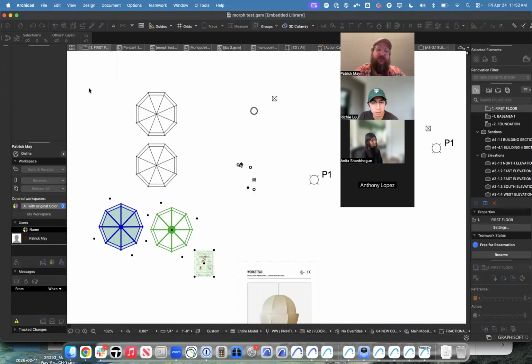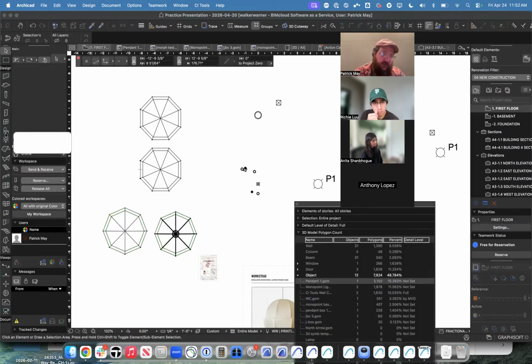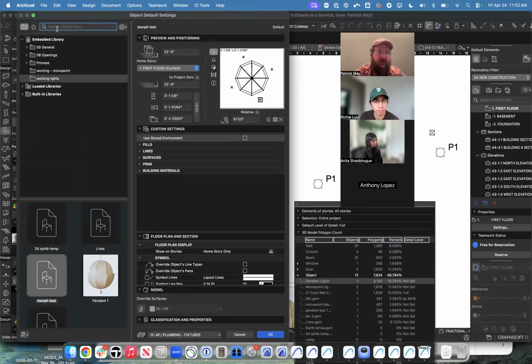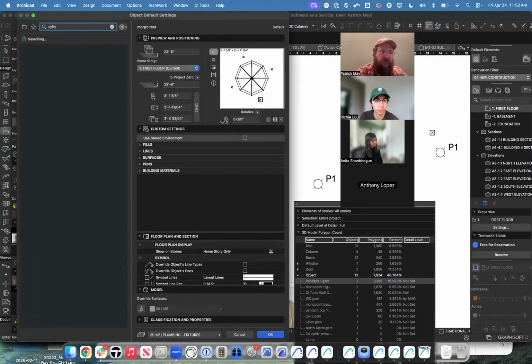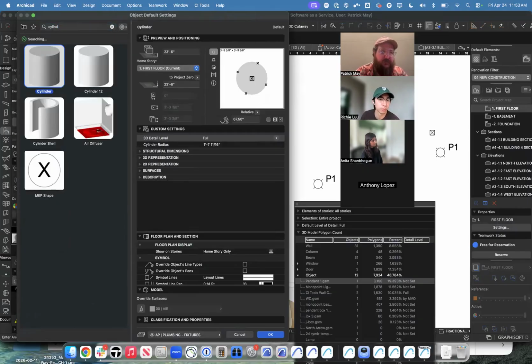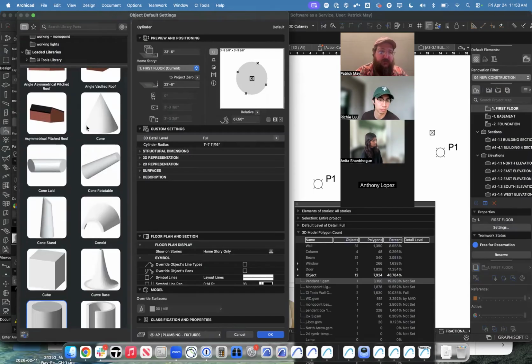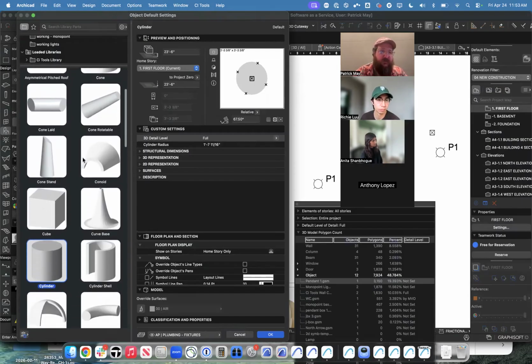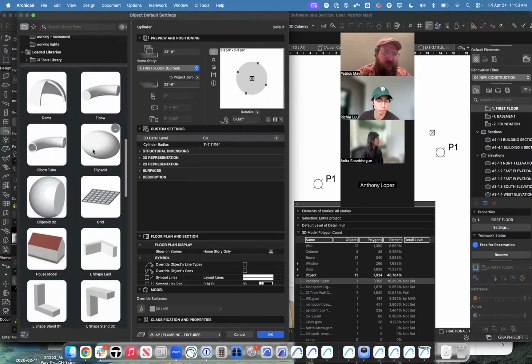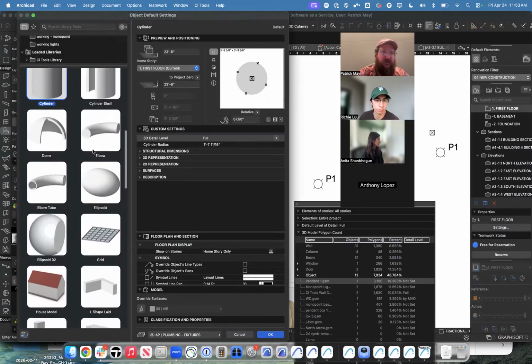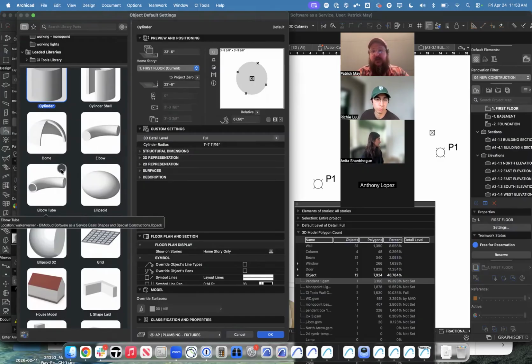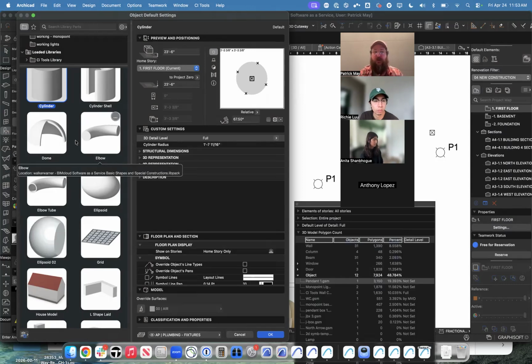Another thing that's useful for creating these objects is, in the object tool itself, there are these basic shapes. These can be really useful, like the cones and ellipsoids and tubes and stuff. I use a lot of these elbows and tubes for plumbing fixtures. The thing about those is you do have to convert those to morphs, because you don't want to save an object into an object. It saves as a macro, and if Graphisoft ever decides to discontinue elbow or dome, your object's broken.